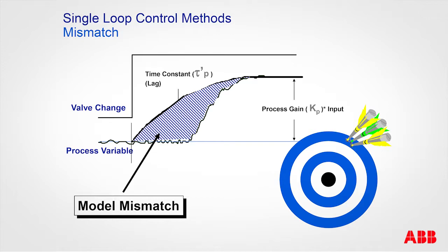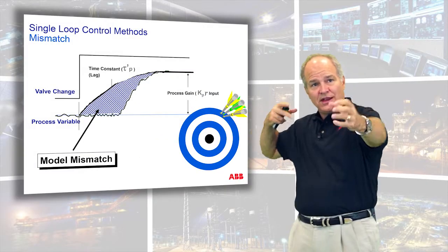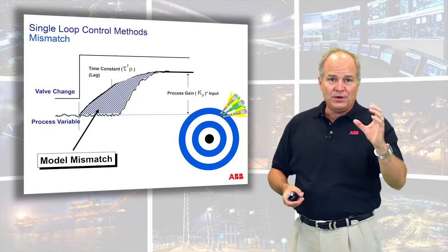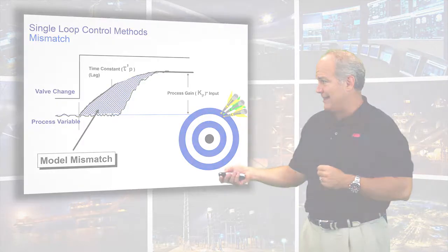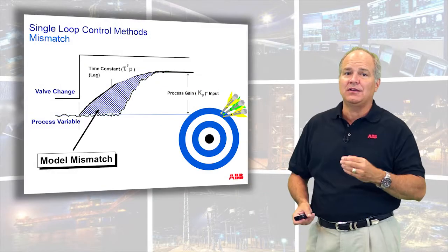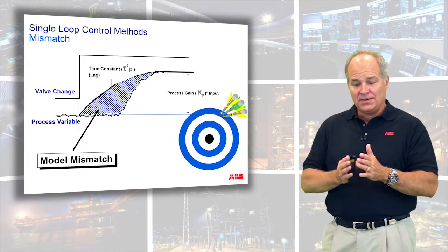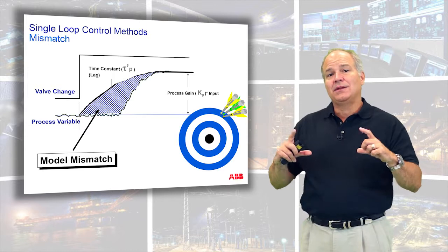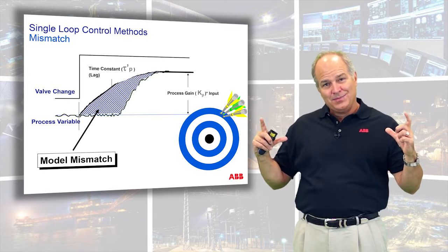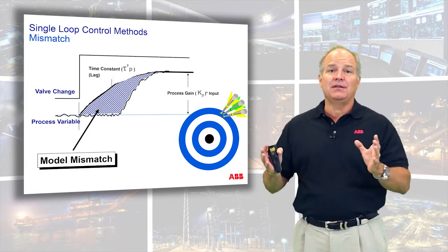And remember, we were talking about the tau ratio kind of allows you to set the target size. It's like if you're shooting arrows, you may group really well, but they are all together and they're not at the center. Our algorithm that we showed, it was assuming that you had a first order response with very little model mismatch. And as your model mismatch grows, you have to make your target bigger. And as your target gets bigger, your set point response or your regulation capability goes down.